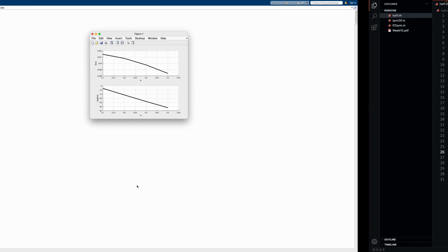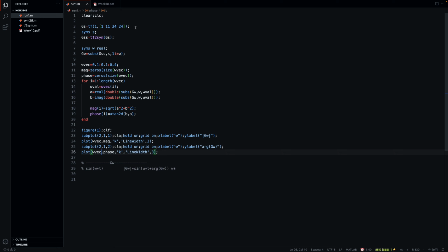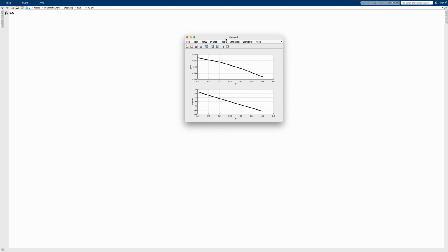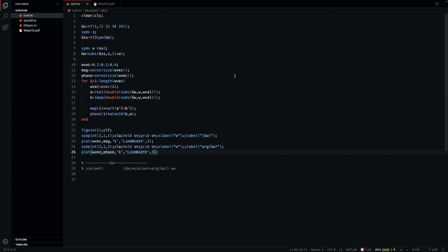So there we go. Now, first of all, this is basically the mathematical way of obtaining the bode diagram, which still doesn't look like a bode diagram, but we'll get on that. But if we think about this here, it could also be generated experimentally, where we have basically a sine generator with input omega, where we change or tune omega with these values, for example, and then we observe the output, and in the steady state we have to measure its amplitude, note that down, and then its phase angle, and then plot that.